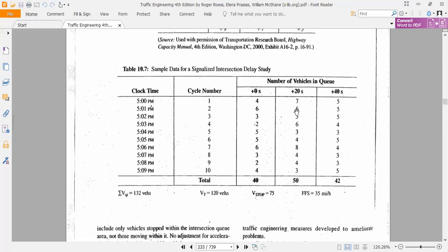Again after 20 seconds the same number of vehicles are standing there. After 40 seconds, the vehicles leave, because only 20 seconds have elapsed, so time is taken by other vehicles to start accelerating and move. Also, you must remember that vehicles are also joining the queue from the rear end, while others are crossing the intersection.